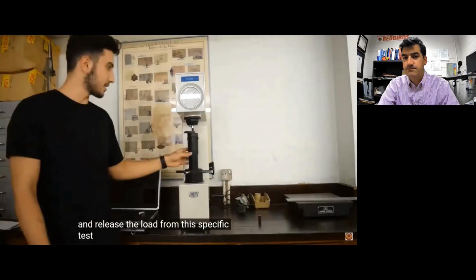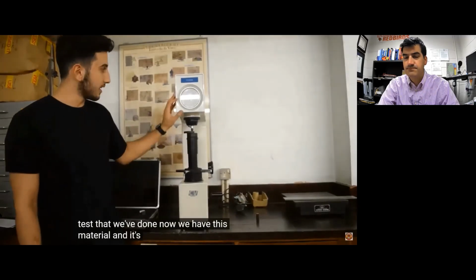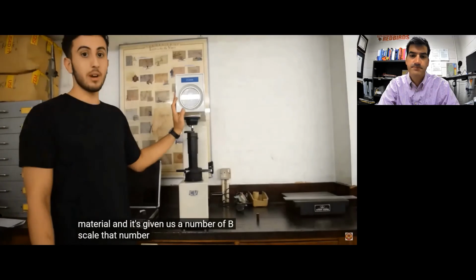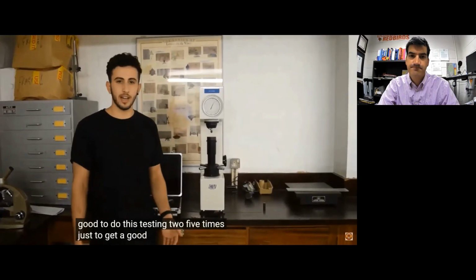From this specific test that we've done, this material has given us a number on the B scale. That number represents the Rockwell hardness number. It's also very good to do this test 3 to 5 times just to get a good average for the hardness of the material. Thanks for watching.